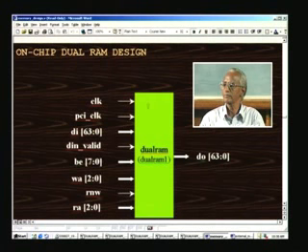And another special feature in this dual RAM is that it arises on account of the requirement for this DCT-Q evaluation. The feature is that when we write into the RAM, we will be writing 8 bytes at a time. So that is 64 bits. We have also said that it is through the PCI interface bus, assuming a 64 bit data bus here. This is for the PCI signal, and we will be writing 8 bytes at a time.